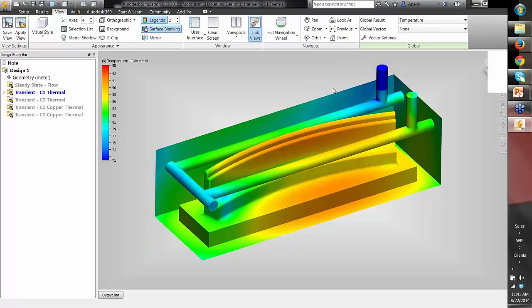In fact, the people I've worked with in the past would run 30, 40, 50 variations, changing all kinds of parameters. So when you're that early in a design stage, leveraging the CFD code is going to get you to an optimal solution faster. Then you can bring that back into Moldflow with your optimized design and do some further DOE optimization,